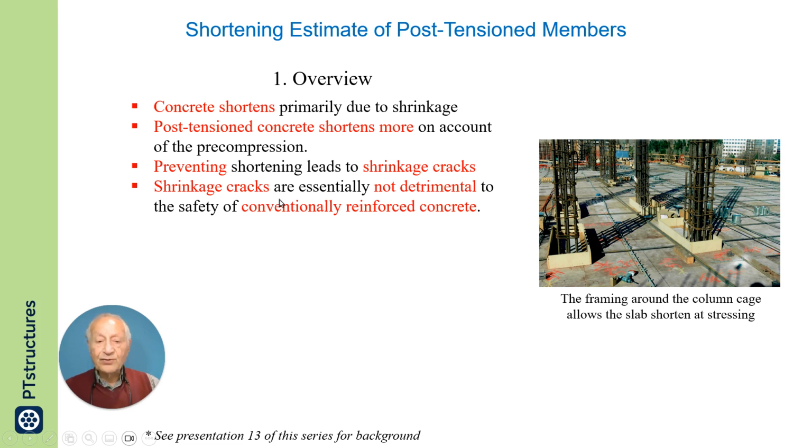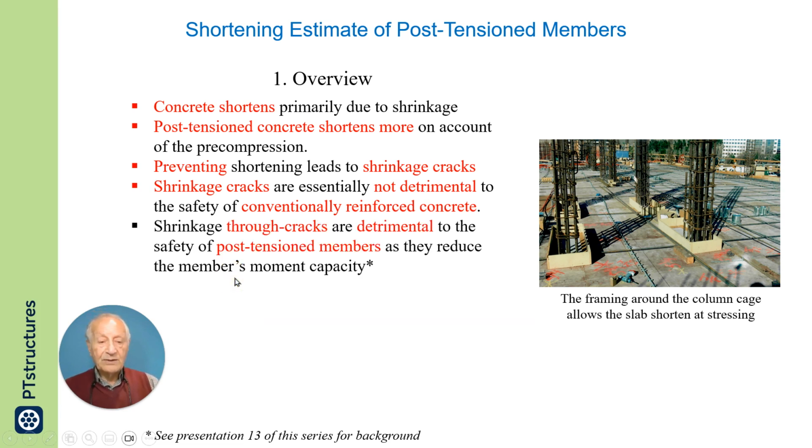Shrinkage cracks are essentially not detrimental to conventionally reinforced members. But shrinkage cracks are detrimental to the safety of post-tension members as they reduce the member's moment capacity.